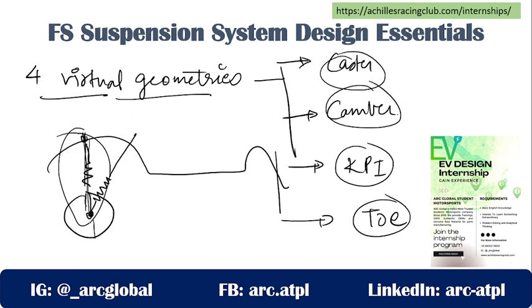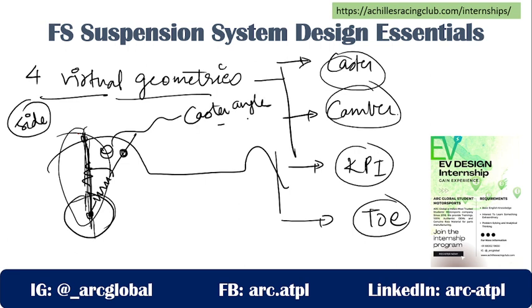From the side view, if you look at it, it's not just about the suspension, it's about the axis about which your tire is pivoting. Your tire needs to pivot to create the steering effort. So if I look at my vehicle from the side, how the vehicle's tire is set up with my chassis frame structure, at what particular inclination, this is regarded as the caster angle.